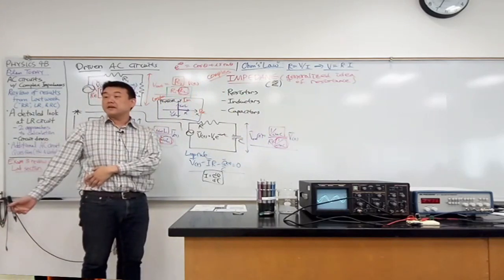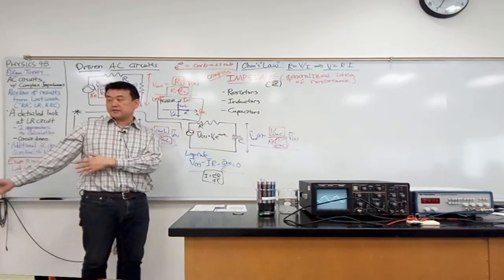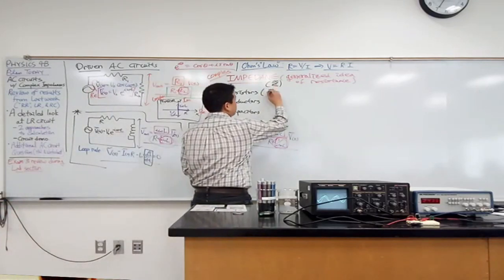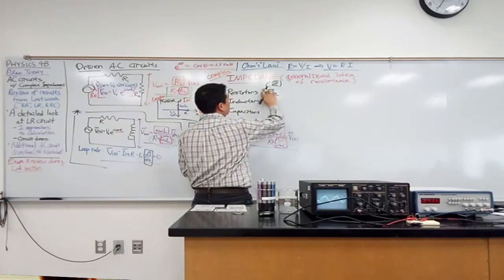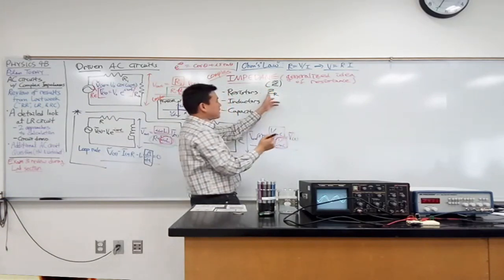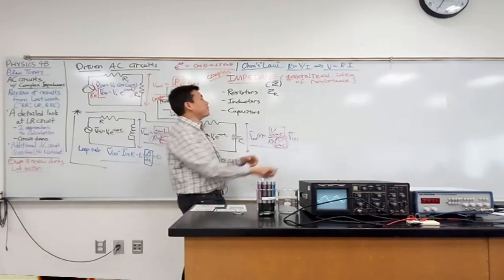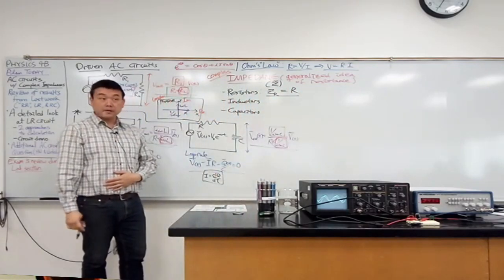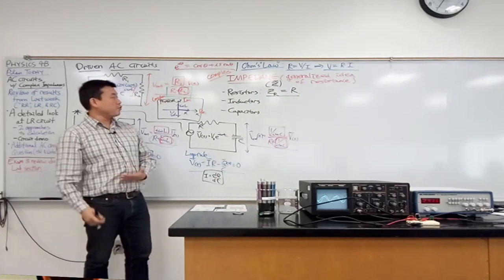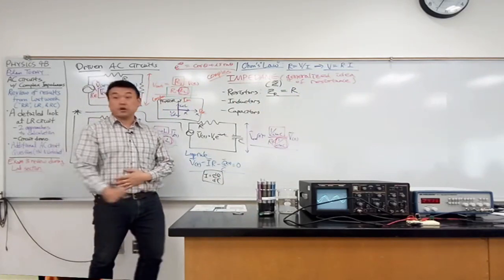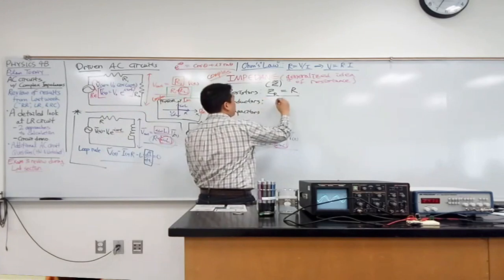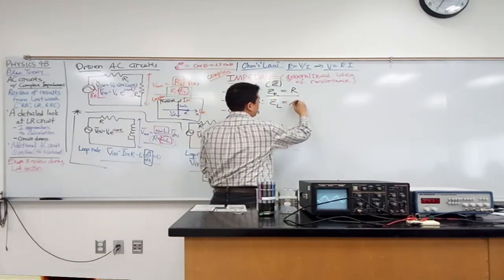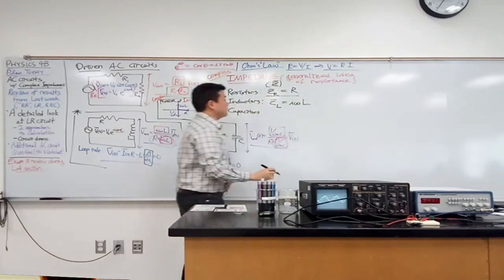Well, it's just resistance. It's just the old idea of resistance folded in as a special case of an impedance. So the impedance of a resistor, this time I'm going to write down no squiggly line because it's a real number. That's simply the resistance. So nothing new there. What is new is what I'm going to describe as the impedance of an inductor. So the impedance of an inductor, L, is going to be i omega L.